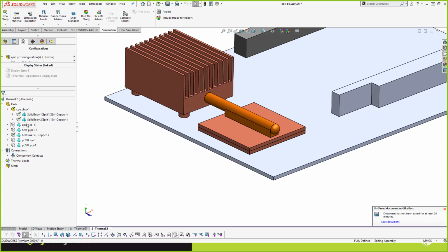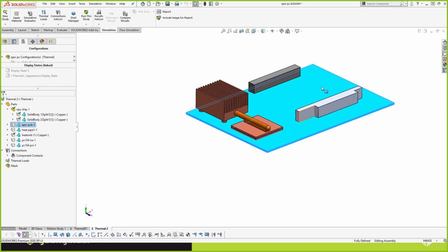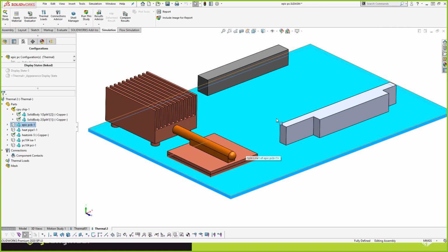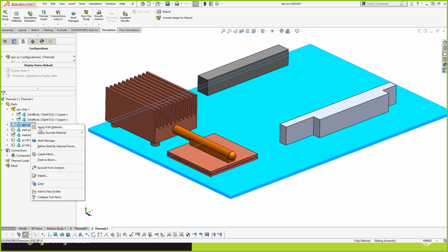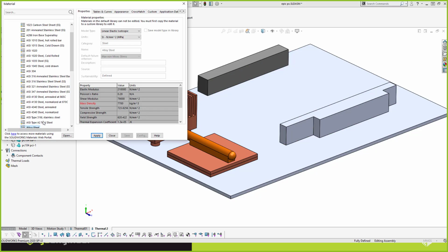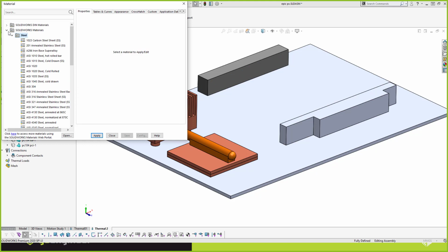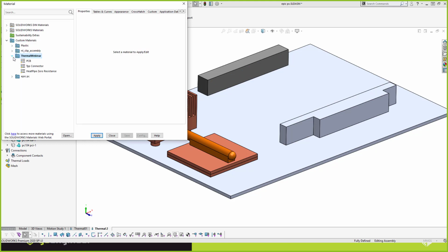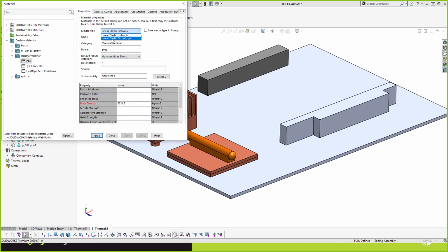As for the board, the thermal resistance of the board is really important for me to model accurately, because that's how heat transfers across this board. And I've done that by using that hand calculation tool built within Flow Simulation or in my spreadsheet. I've come up with an orthotropic material that has these conductivities across there.